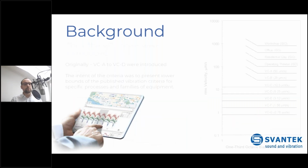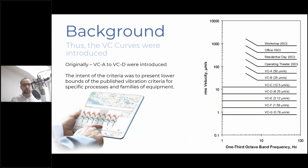So Colin Gordon developed the VC curves, as shown on your screen right now, as a frequency dependent threshold, a vibration criteria that you need to fulfill when creating a space, when creating a laboratory, or creating a manufacturing site. You need to fulfill these criteria in order to ensure that the space you created will be able to perform that operation without any negative impact. Initially, VCA to VCD curves were introduced.